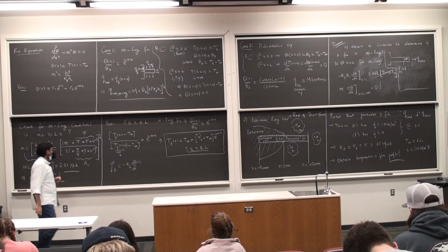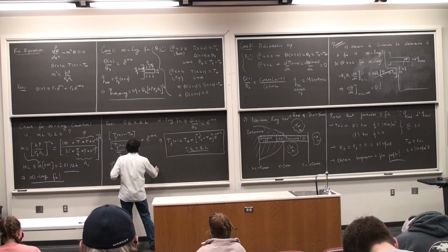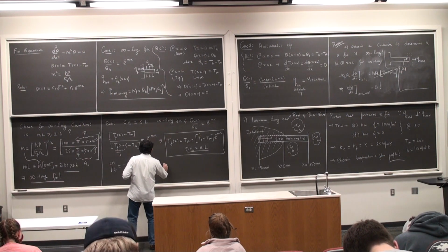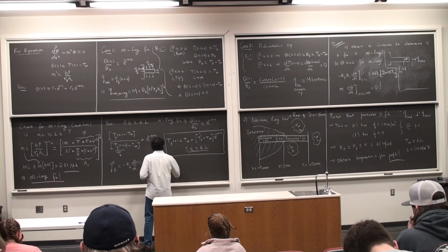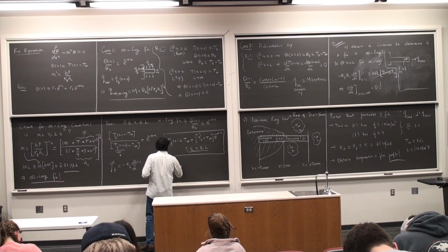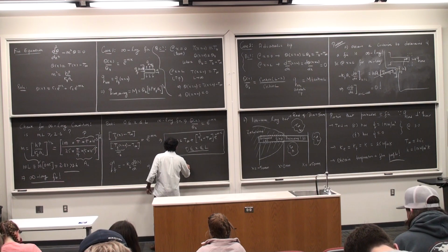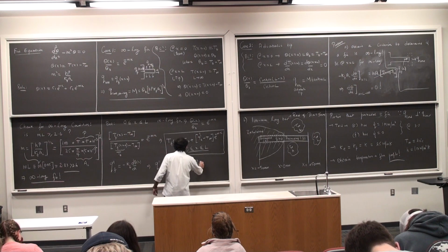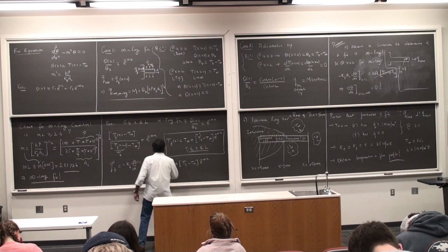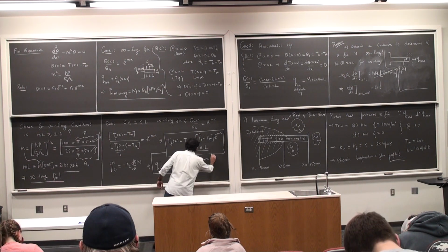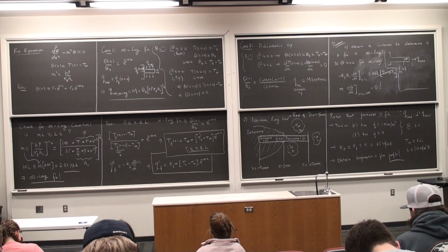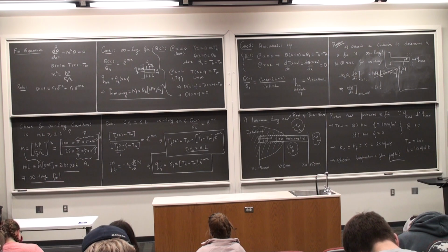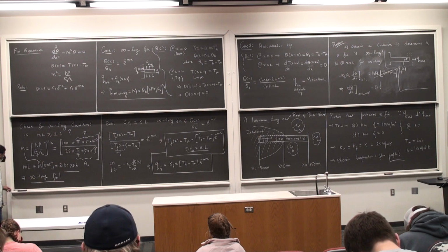If I do the differentiation of this expression, Q double prime fin is going to end up being the following. So this is going to be Kf times little m times (T base minus T infinity) e to the power minus mx. And I want to see if there are any questions so far. All I did was take the expression for Tf and then differentiate it. Okay, so nothing fancy.